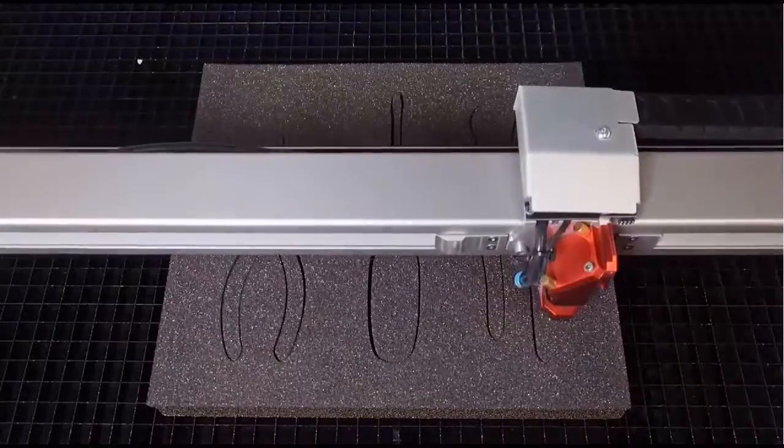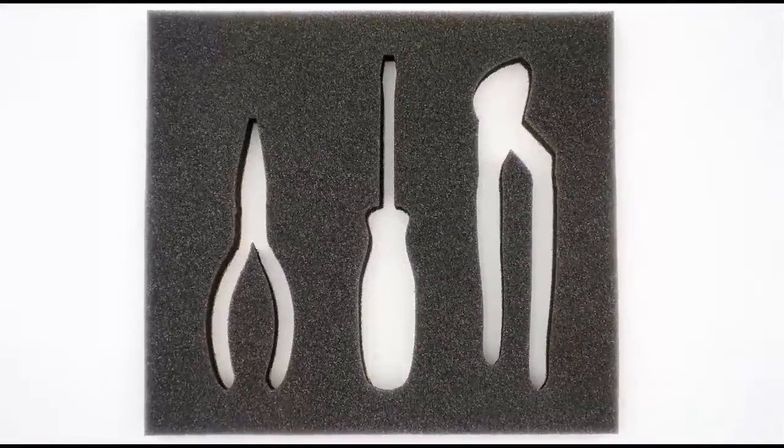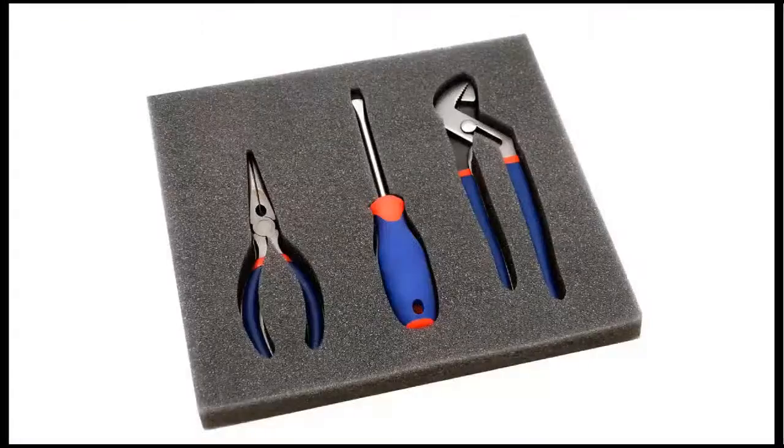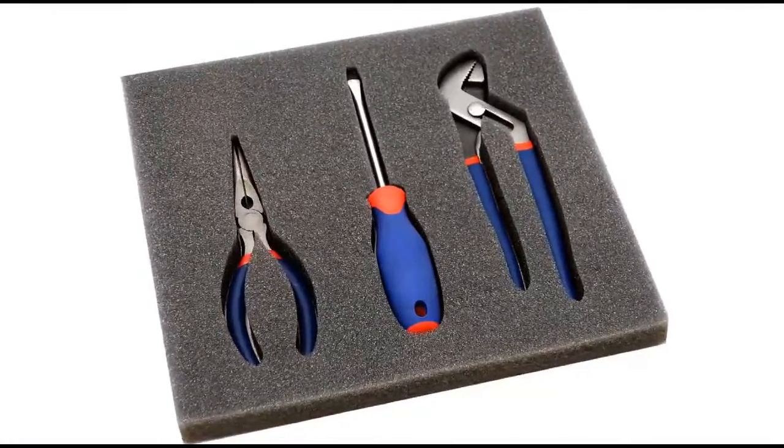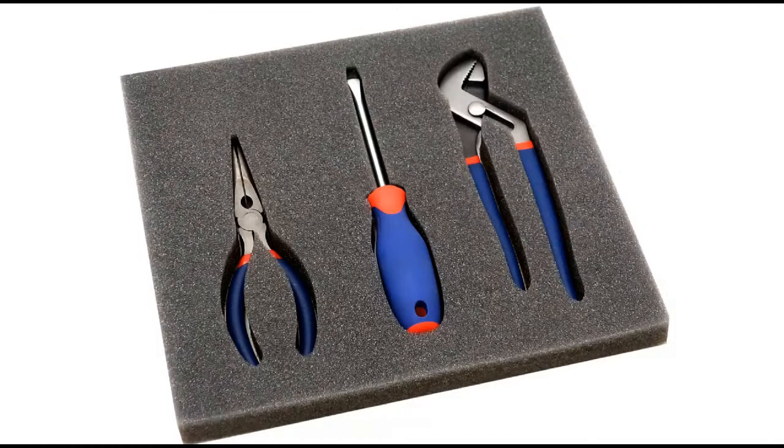But I now know I didn't even need to double check measurements by any means after I was done tracing around this, because I know the scanner is going to be a 1-to-1 ratio. You can do this with a camera. If you take a straight on photograph and then trace around it with a camera image, I do suggest measuring your tool afterwards to make sure that you don't have any angling or skewing or scaling, because the graphic will be skewed quite a bit if you don't get it perfectly straight on with your camera. And it'll also come in much, much larger.